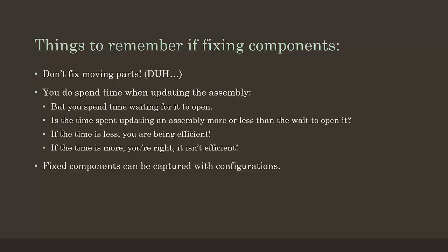So I haven't tried it, but what I'm wondering is that whole thing where I said you have to float a component and then fix a component. I'm wondering if I can actually have a configuration where I say float everything, let it update, and then fix everything. It's going to take an hour or two, but maybe it's one of those things where I do a bunch of changes, let it kick off for an hour. That's still better than sitting there waiting for an hour for it to open up every single time.